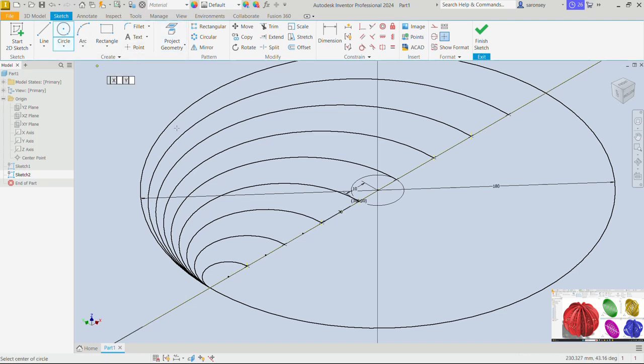Now I'll pick the circle command. Let's draw a circle from those points. You know you are there when it turns green, just click and drag. Let's specify the diameter of this as 6 and we can enter. We can also draw another one here, and then there you can use the pattern command, but that is fine. Let's just go through the pain of drawing all of them. Okay, that is it.